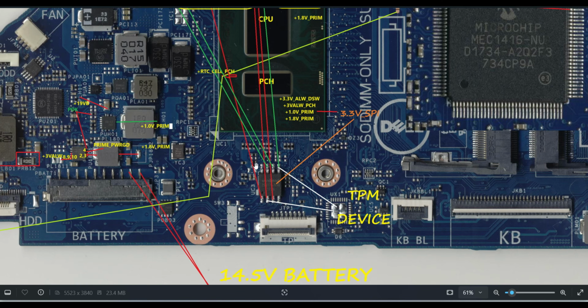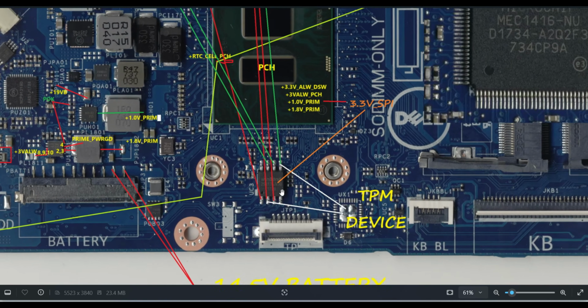As per this pin, one or two signals will enter the TPM device. At present, this particular motherboard doesn't have it, so you are getting a TPM error, right? Because of this only. In case this TPM device is faulty, or some of the program has got corrupted in the main BIOS chip, then you will get this kind of error. Okay, TPM device error. Usually in Dell Latitude and commercial series we can check these things.